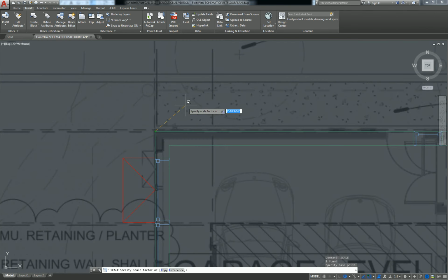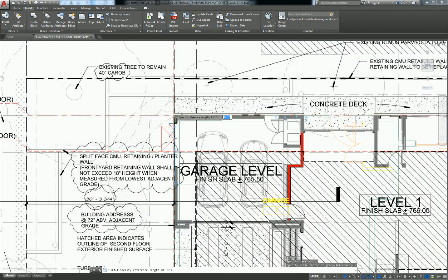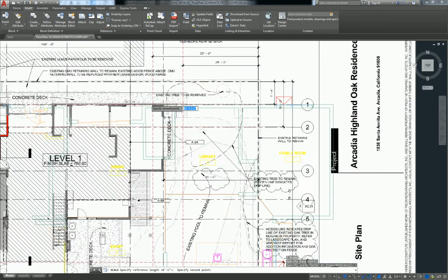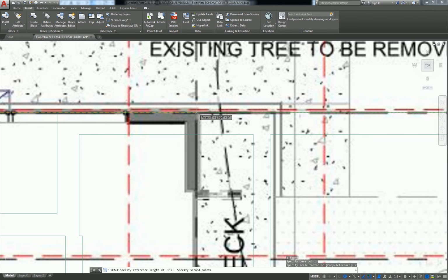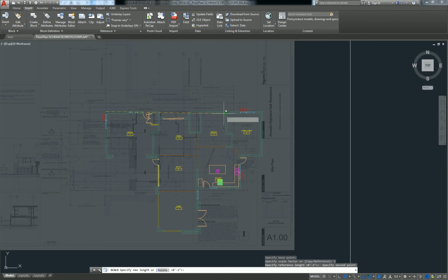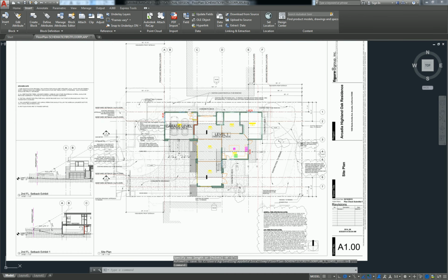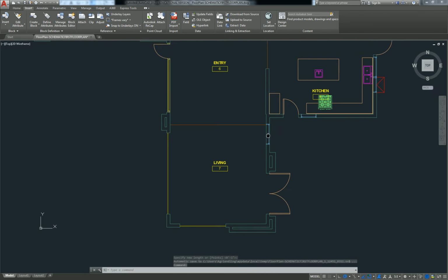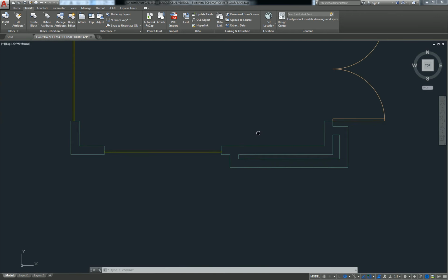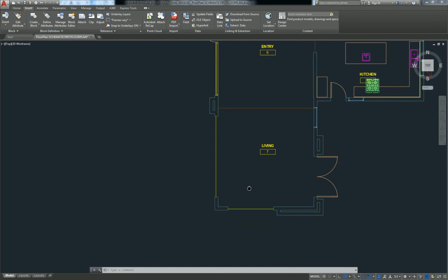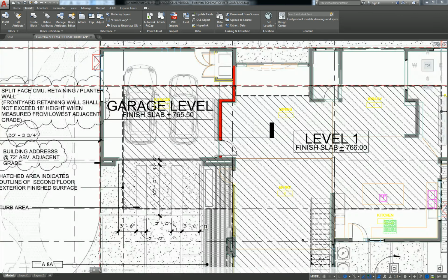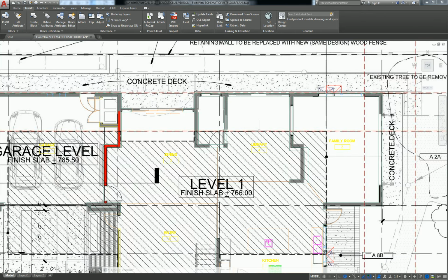I'm going to pick a base point, hit R for reference, pick the new base point, then pick the reference distance, and then pick the new distance, which will be that. In theory, if you scan around the exterior of your building, it should fall pretty much exactly on where the exterior walls are, which for me is pretty close, and I'm comfortable with that.